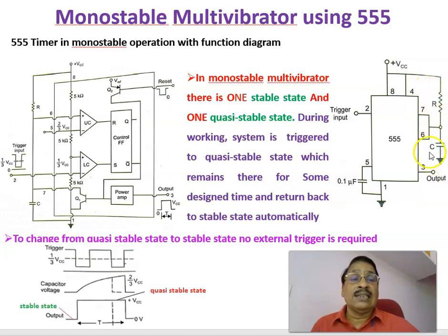Therefore, the value of the resistance and capacitance is externally connected. That will be deciding this time period. I shall be explaining that one. And here the trigger signal is connected to pin number 2.